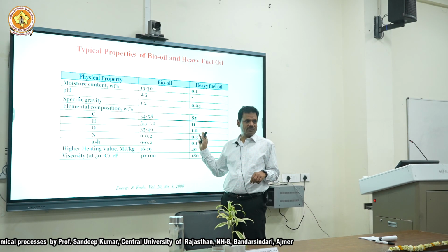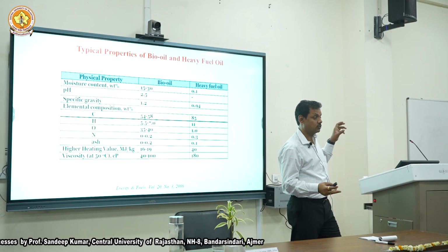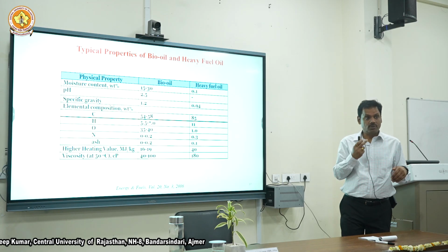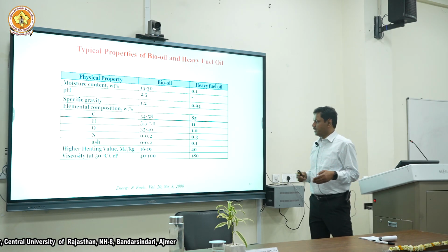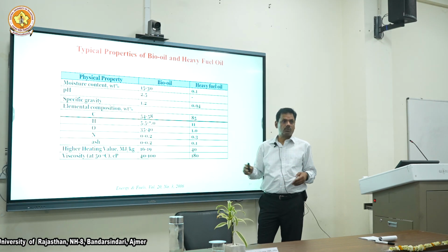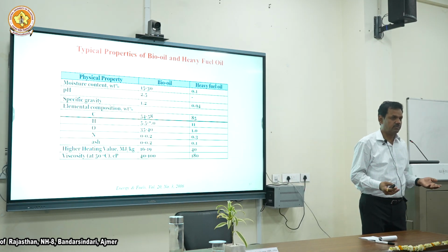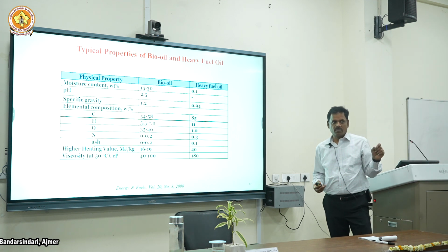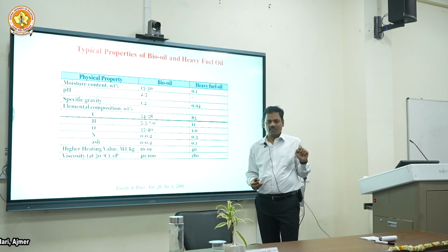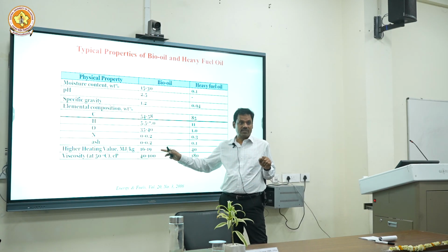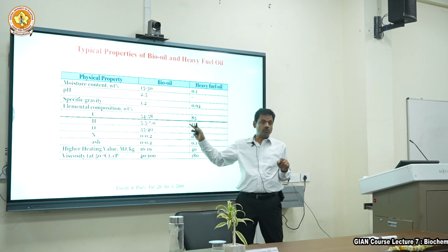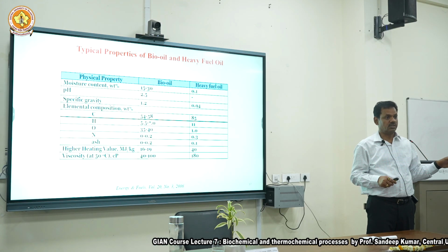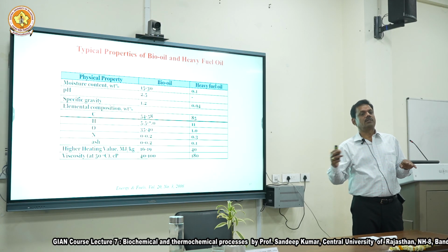So you can get confused. But now you need to say that we wanted to turn solid to liquid, which is easier to handle, easier to store, and then it is easier to do upgradation. Upgradation means from here to here we can do now. It's a liquid reaction, liquid gas, something like that. It's not solid. Okay? And remember, biomass is hydrogen deficient. So this is still hydrogen deficient. You need to add hydrogen, but now you can conduct a hydrogenation process to upgrade. So that's why making pyrolysis oil is one of the options. It's an intermediate process, turn into liquid and then you produce.